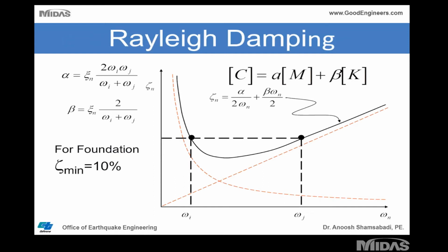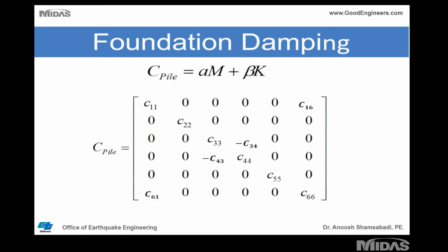And it's an iterative process because the stiffnesses are developed for a given displacement. We don't know what kind of displacement we're talking about. That is the drawback in the substructure model: you have to guesstimate a stiffness based on a given displacement and go back and forth until you converge to a stiffness that you like when you look at the global model.